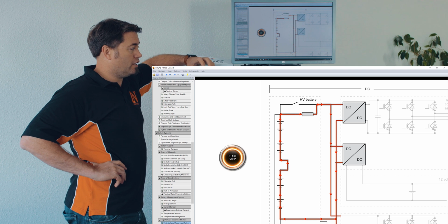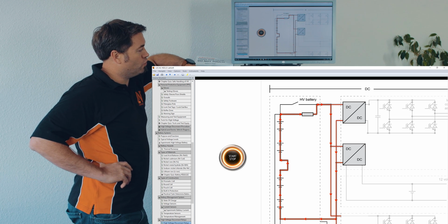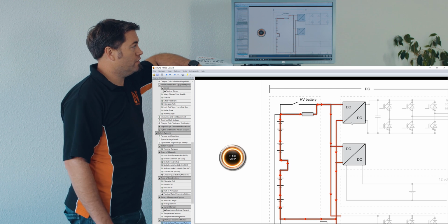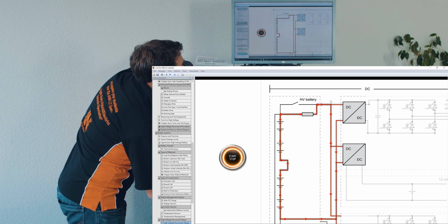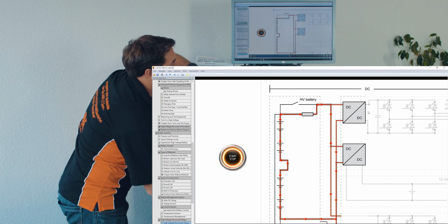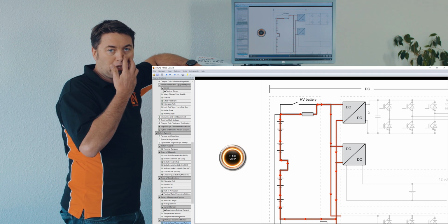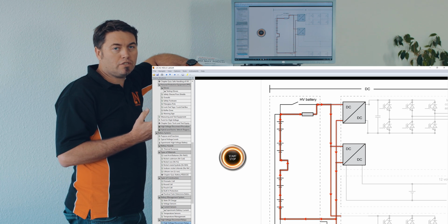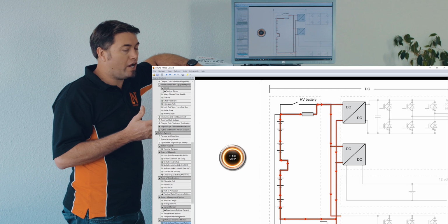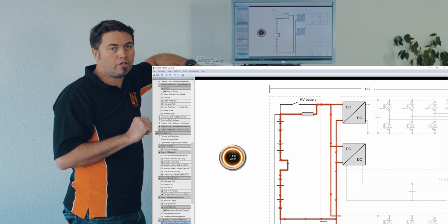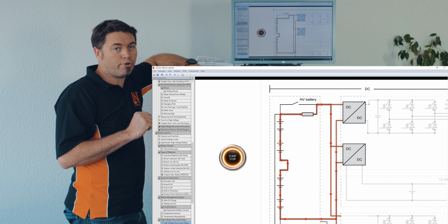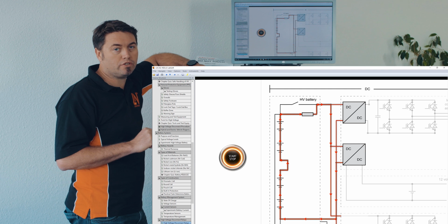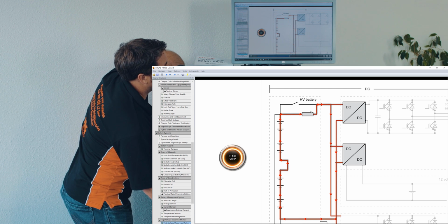If there's something wrong with that, let's say we've got a short circuit within the air compressor or in the inverter, then without this relay, we're going to get full power going to the short circuit. We know that when we have a short circuit without any resistance, we're going to get full current available from the battery going through that circuit. And that's going to create some pretty massive damage. It will melt all of the cable, all of the wires, destroy the system. So that's why we use this pre-charge relay.